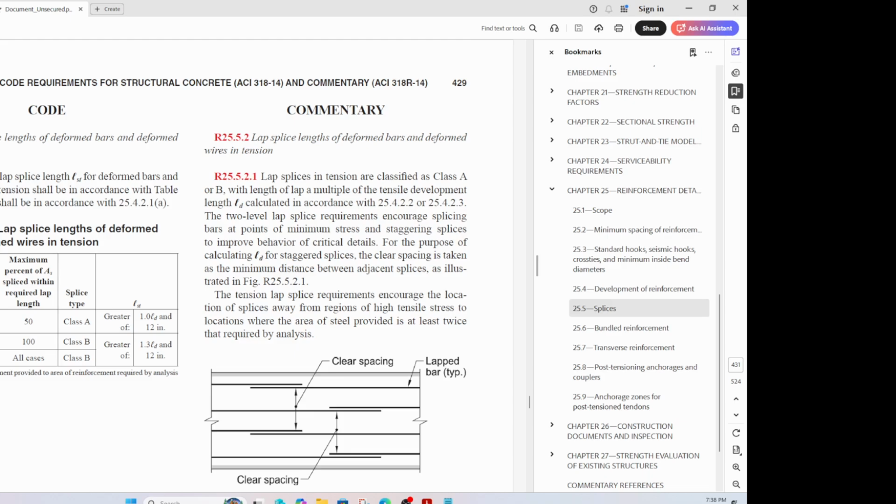Area of steel provided, area of steel required. What is this? So let's say you have a building, something like that, and you have your columns like that, and then let's say wind is blowing from this side, correct? When wind is blowing from that side, everything wants to lean to the right. So let's say your bending moment diagram in the column is something like that in all these columns, right? Nothing is to scale. The channel itself is chicken scratch, so we're just doing chicken scratches here, right? So the max moment obviously is here. Let us say this is M.